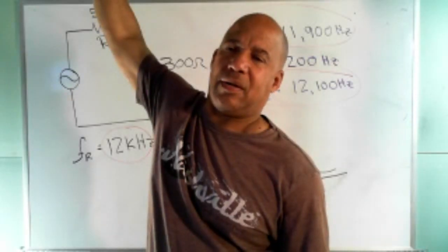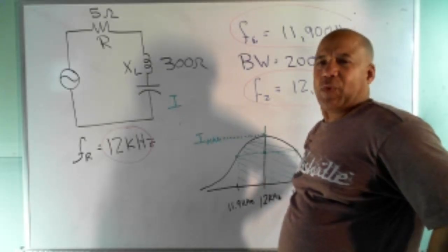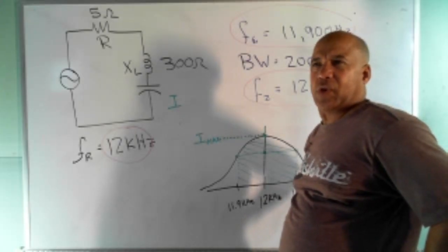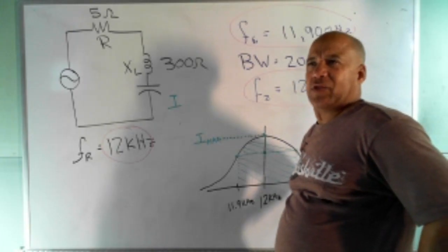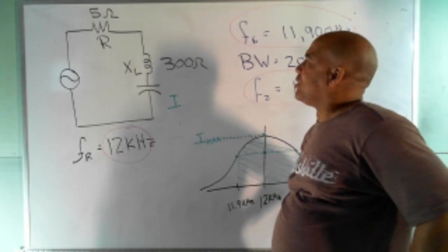So you end up with half of the power when you take RMS of the current and RMS of the voltage. 1 over square root of 2 times 1 over square root of 2 is exactly half. So with the RMS voltage and the RMS current, to get your power, it ends up being exactly half power. I get it. I think I follow what you're saying.